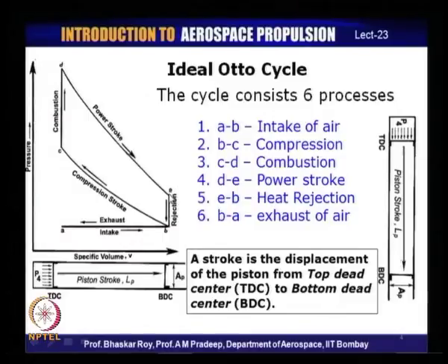And in the ideal cycle, conceptually, between A and B, you can say that there is a certain amount of heat rejection which occurs from the system. Just like there was a heat intake into the system through fuel burning, there is heat rejection through various kinds of heat transfer, and then the process reaches B, and from B the air that has been inhaled is now exhaled, and the exhaust of the air goes out of the system, and then fresh air is brought into the system. So, this is the cycle.